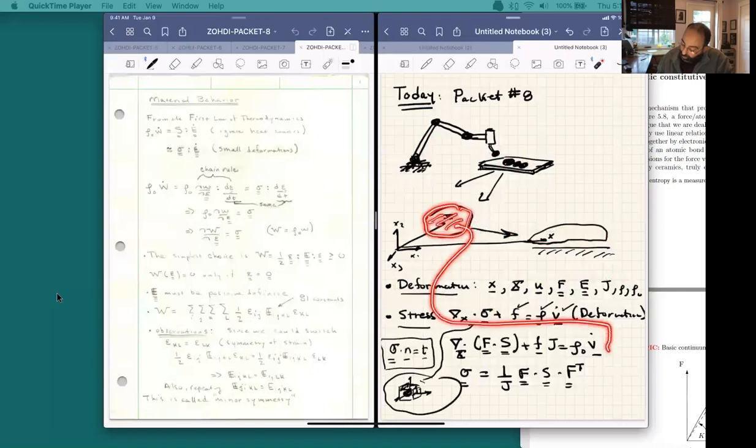If we do that, we get a slightly different differential equation that has similar form, but it now has this quantity called the second Piola-Kirchhoff stress, which is related to the Cauchy stress by taking 1 over J, F times S times F transpose. We can get then the S, we multiply that by F, we take then the derivative or the gradient with respect to big X. Notice the difference between that and little x. We have the volumetric forces that are scaled by the Jacobian that also comes out of the transformations in the calculations. We have the original density, and then we have the time derivative of the velocity.